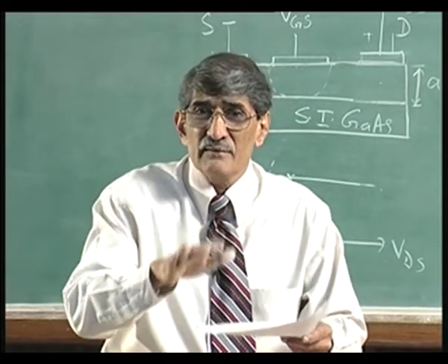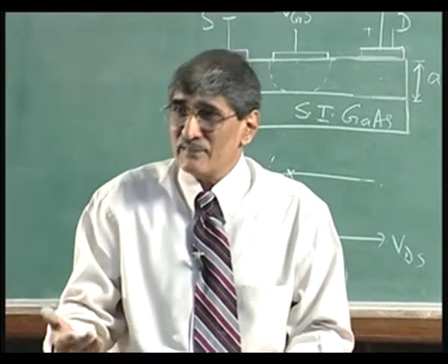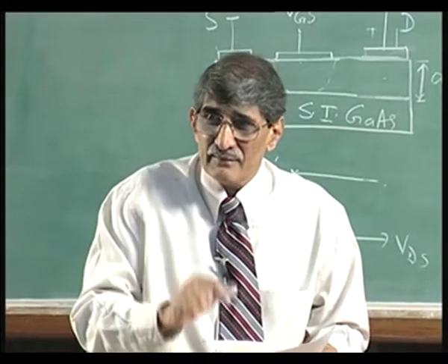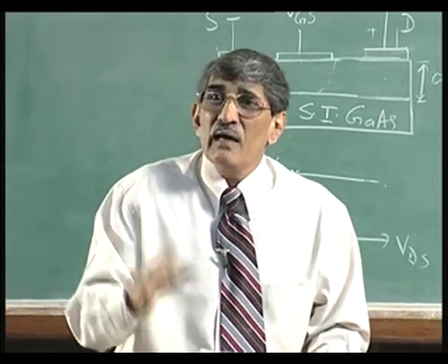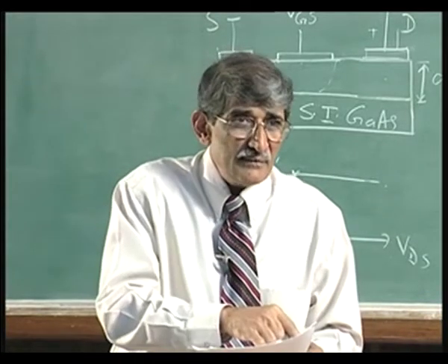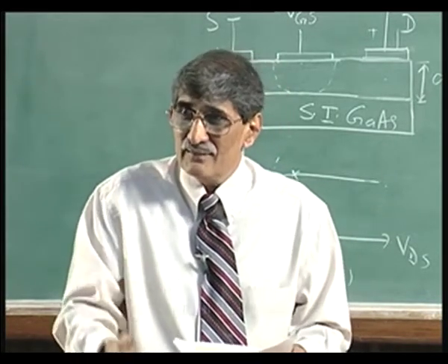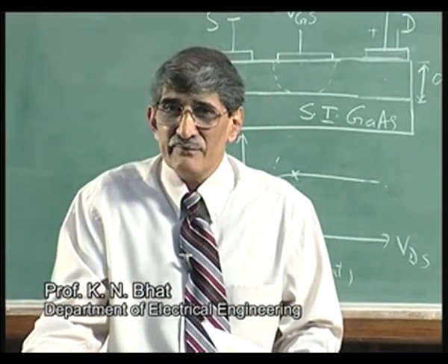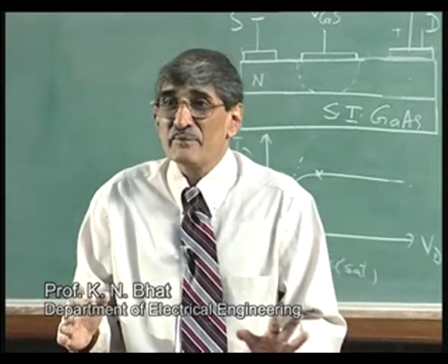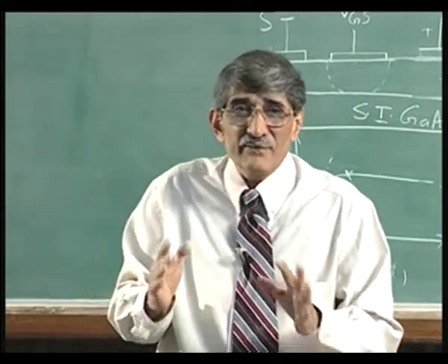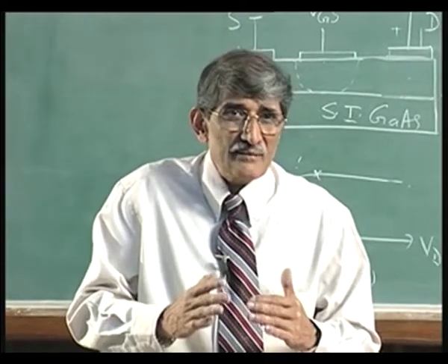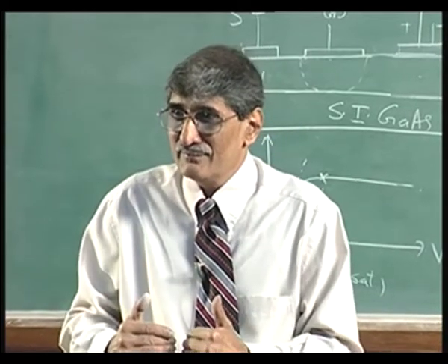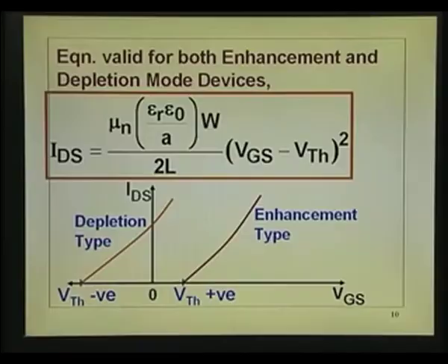So, the uniformity, this is the problem which you are passing on to the technologist, asking the technologist to say, I want A to be the same everywhere. In the case of JFET, MESFET, I want A to be the same everywhere, and I want the T oxide to be the same everywhere in the case of MOSFET. I want the doping to be the same everywhere in the case of JFET, MESFET and MOSFET. Those are the problems which make life difficult for the technologist. So, the final heat is taken by the technologist.